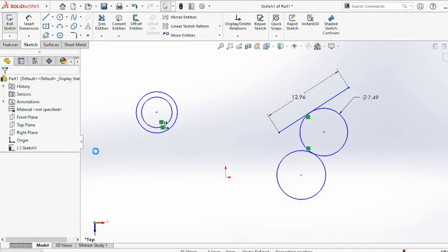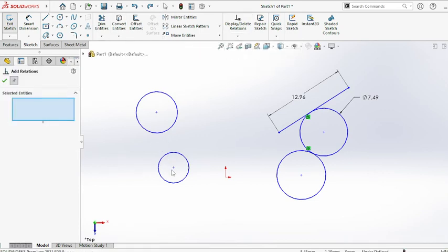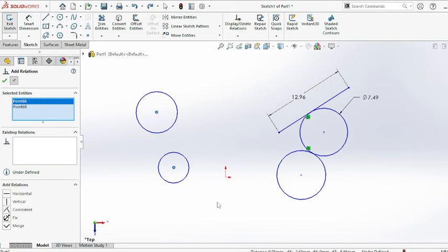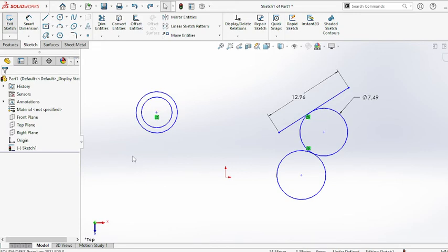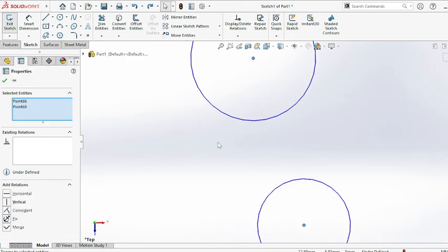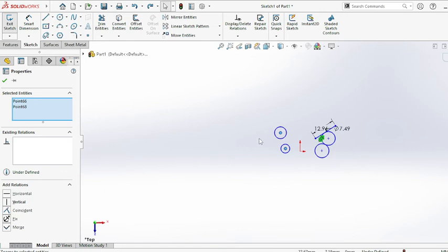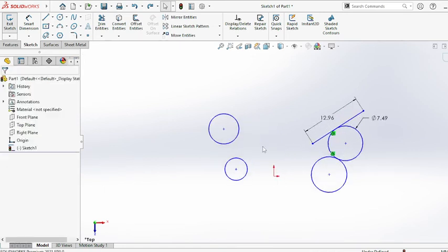Okay, so for example, here both the circles are there. You can go to the add relation. I want to select center and center, both having coincident. You can select the center point, that time you can use the coincident option. Circle is called concentric. Okay, these options are also important in assembly, the constraints. Okay, what is concentric, what is coincident? Okay, you are not forgetting this.